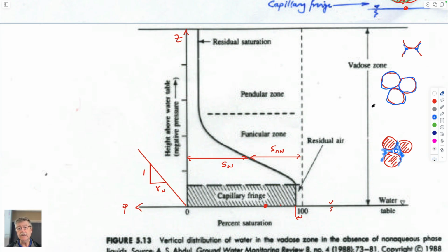So just now the bubble in here that's evolving is the air. And as the air grows, as you go from the right side to the left, the saturation of the non-wetting fluid grows as you go that way. Then more of this space becomes bubble. So the bubble grows until it essentially excludes the water, and then you're left just with these pendular rings. And so that's entirely logical from what we've talked about. And we can get the saturation of water as we go up from here.